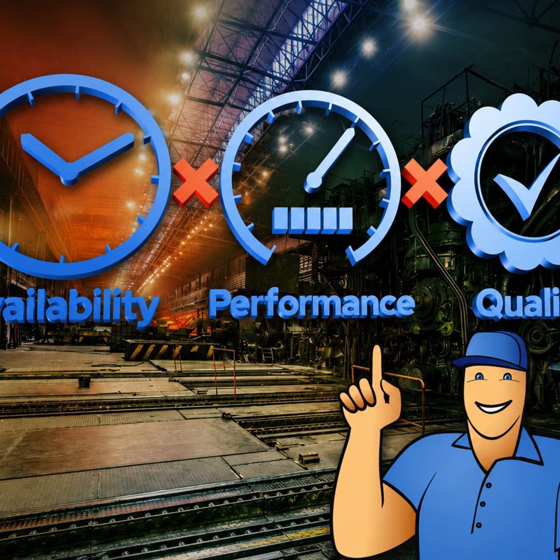Performance. How fast did it run? The performance factor measures how fast the machine or production line was running compared to its theoretical ideal speed, or its design production speed. In other words, even if the machine was available and running, was it running as fast as it should have been? There are two common ways to calculate performance. The first formula is performance equals ideal cycle time times total count divided by runtime. Another way to look at it is performance equals actual output divided by the theoretical maximum output during runtime.